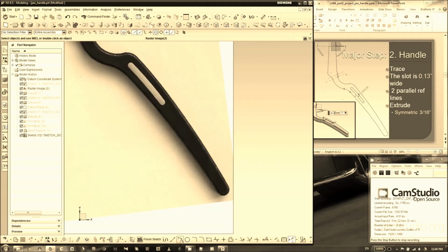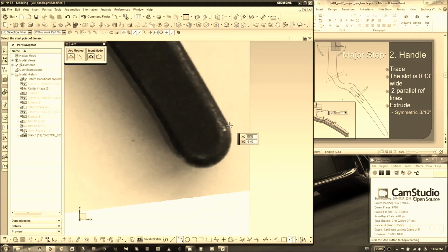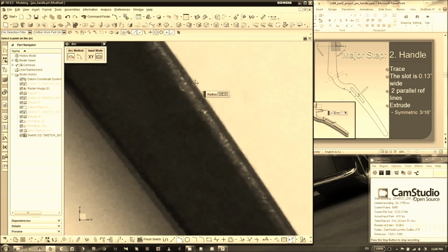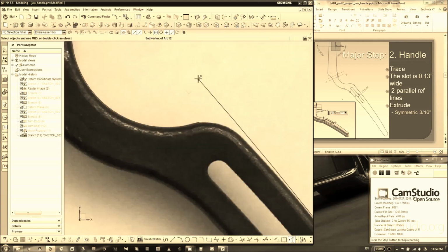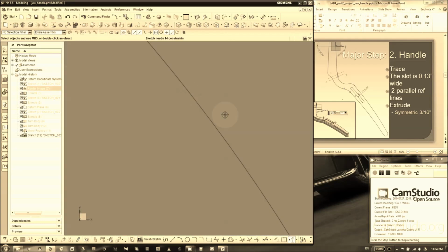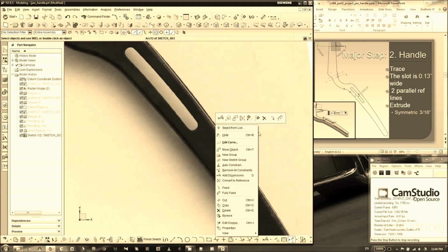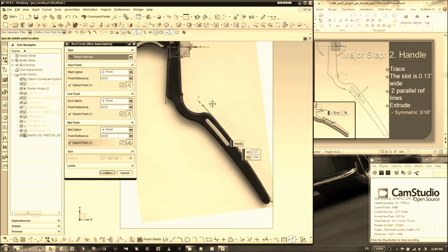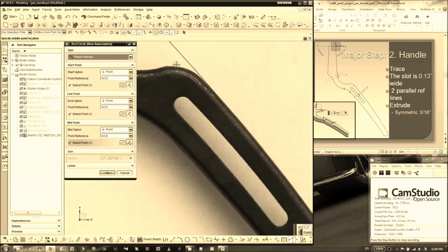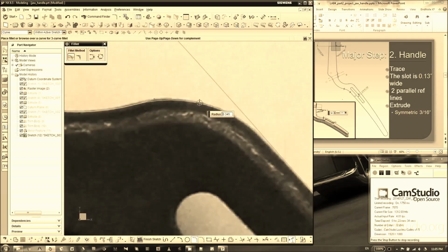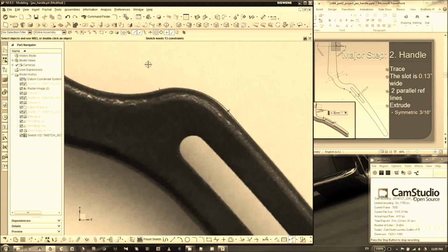And we keep going to the right side, which is a really big arc. So let's make this point all the way to about, look at the intersection here, about here. Then let's match in the middle. And if you feel this point is not very right, we can adjust, then drag the middle out a little bit. Or you can right click and where's the modify. Okay, edit curve. Zoom in and zoom out. Okay, that's pretty good to me. Just click OK, and we're gonna put a fillet here, which should match nicely to the image.